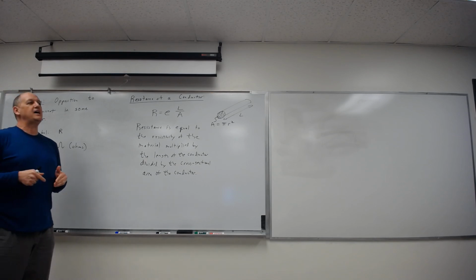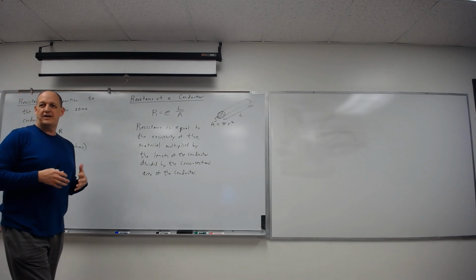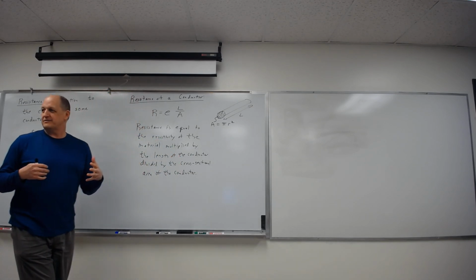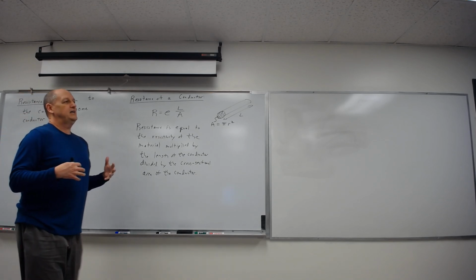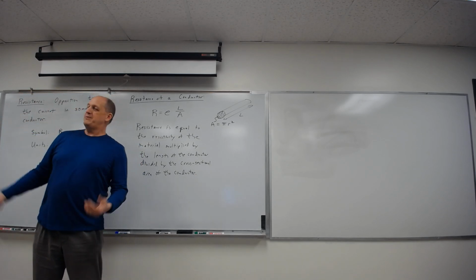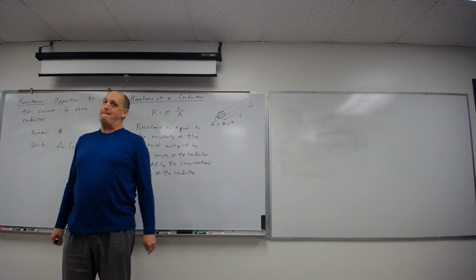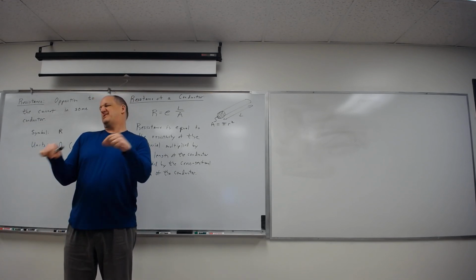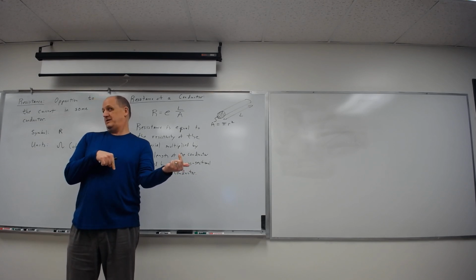So I decide, we're in Kansas, so let's do a wheat field. We're going to have a big, inexpensive, we're going to try to do like Woodstock 2025 or something, right? Go to a wheat field. And we run power out there. And I get there and I have power, no problem. And I run a 1,000-foot cable out there and I measure on the end and I go, I have 100 volts here. All my stuff is designed for 120 volts. Probably just fine at 110 or 130.